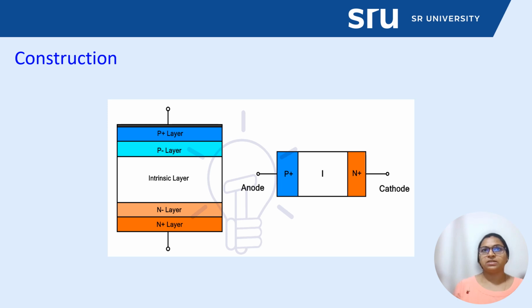In reverse bias, the voltage pulls carriers away, widening the depletion region across the intrinsic layer, and this blocks the current, and the P and N layers store charge like capacitor plates. The intrinsic layer will act as a dielectric, yielding capacitance. So this makes the superiority of the PIN diode to use as an effective switch or capacitor in the reverse bias.